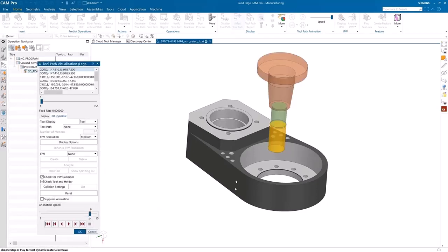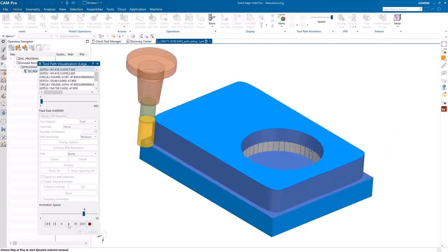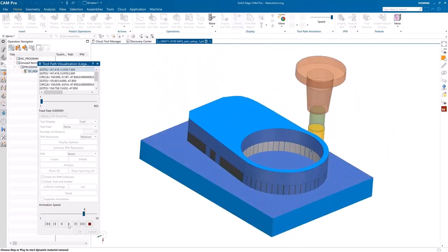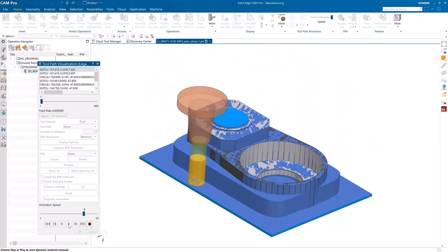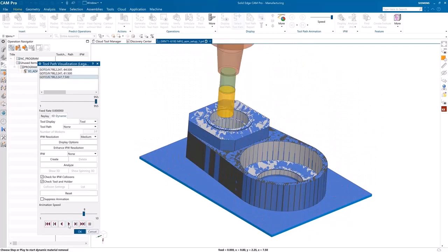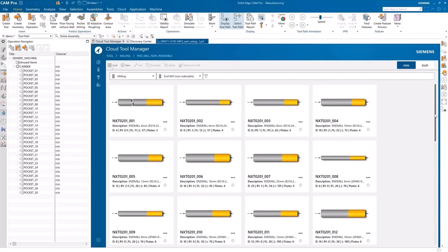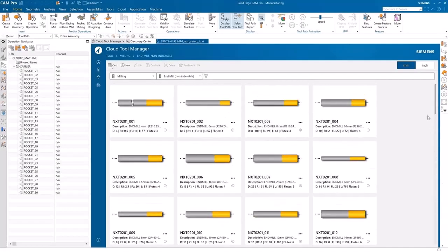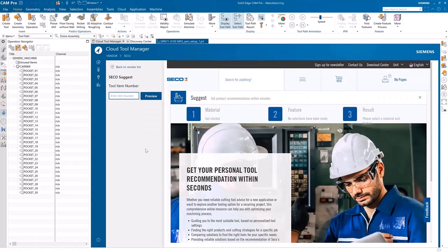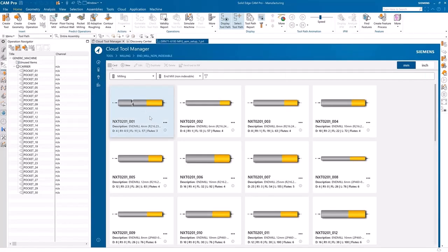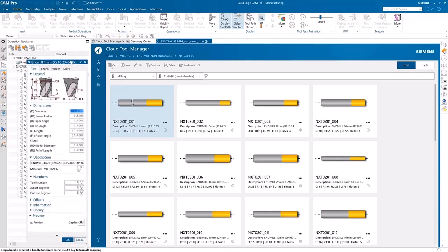It reliably and dynamically checks for tool holder collision when the tool moves within a region or across multiple regions. Toolpath generation is faster, bottom-up cutting has been enhanced, and a top-off flat faces option has been added for faster throughput. The Cloud Connect tool library, as the name implies, stores cutting tools in the cloud database for easy access. Tools and holding devices can be easily searched, downloaded, and modified. Immediate access to cutting tool vendors is also available from the same location.